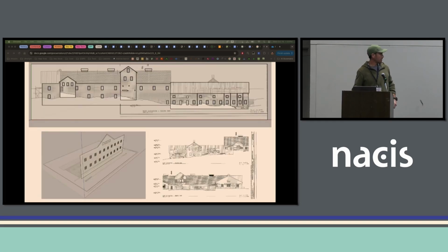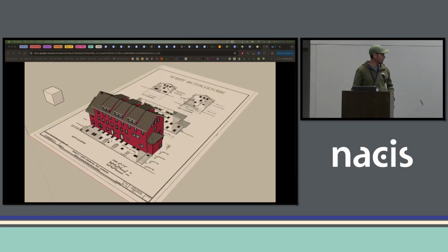And this is kind of what it starts to look like. So I'll bring these into SketchUp. They're flat planes, and I'll just start to draw them out in 2D. So each wall, each side, not every building has each side represented. Sometimes I'll only get one side. Sometimes I'll get two sides, like a north and a west, or an east and a west elevation. And then I'll tilt it up, just like you're building a Walmart, and tilt up all the different sides.